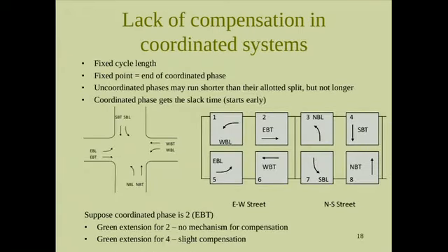But then there's another basic paradigm for control, which is coordinated control. In the US, I'm showing the most basic paradigm, which is the dual ring with 8 phases. I'm not including right turns because right turns usually don't have their own lights. The right turns just go with the through movements. And with coordinated control like this, we have EBL, that means eastbound left, and WBT, westbound through.